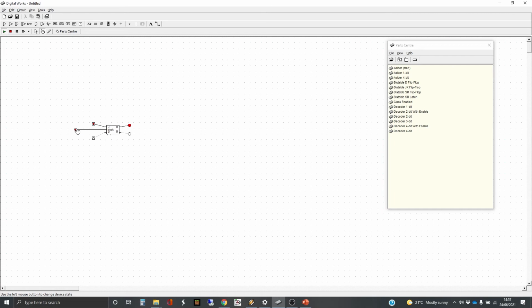So J works as S, K works as, let's disconnect that one, as a reset. So when it goes low, it'll switch back. Yes, thank you. It is doing what I said. And when we have them both high, every time it goes low, it switches. So this is different behavior from the SR flip-flop, different from the D flip-flop, and it actually does what you might call